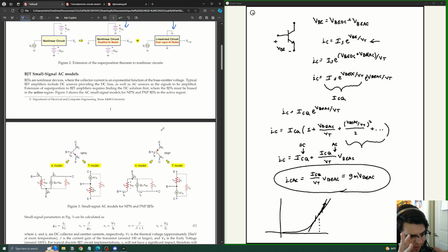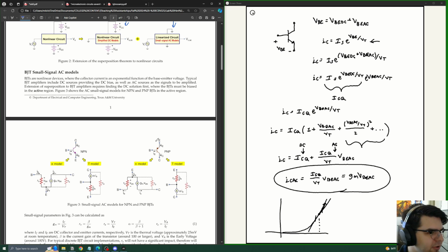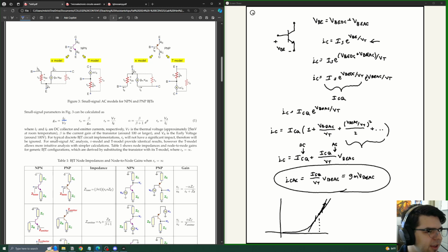And then after, the deal is that we've biased the BJT amplifier to be in active region, right? And then the small signal analysis that follows after that uses those characteristics, right? So talking about IC, like the quiescent current, right? It sets what all these variables are going to be after we apply our small signal model, so that we can look at what happens to the current as we bounce around that linear region, right? So that's the development of how we've created the small signal models to simplify the analysis.